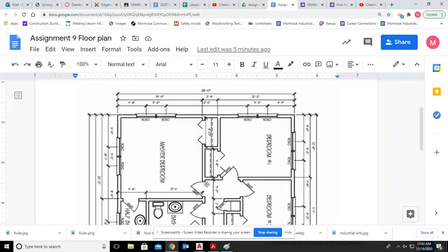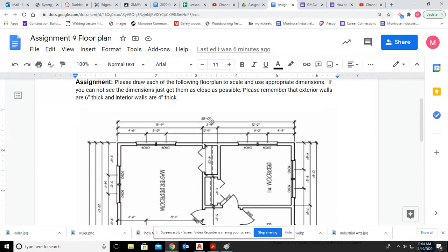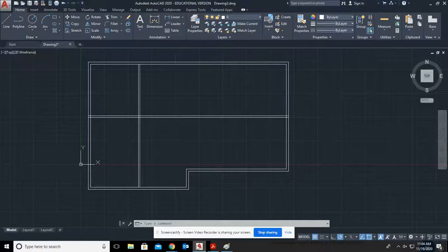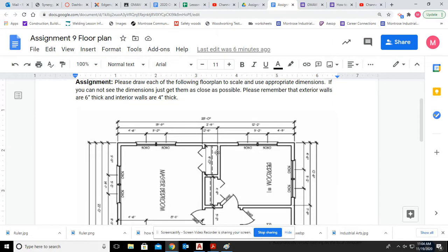So I would suggest we do these lines next. Now if you choose to do something else, it's not necessarily wrong. You've got to determine what the best way or easiest way is for whatever room you start drawing. So I'm going to draw this line so that I can go ahead and finish up this region of the house. So if we look at this again, there's another measurement. We can come from that side over, or we can go from the outside of that bedroom wall over, it looks like 2 foot 5 inches. 2 foot 5. So back here we're going to go 2 foot 5, and that is from left side to left side, so outside to the opposite outside.